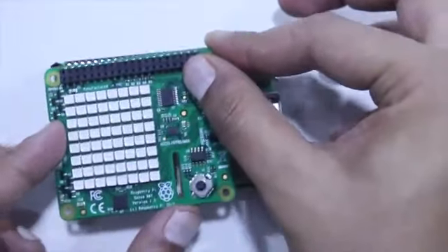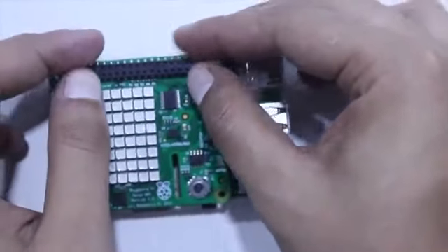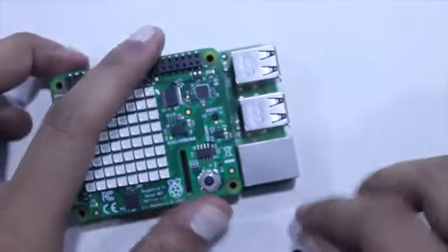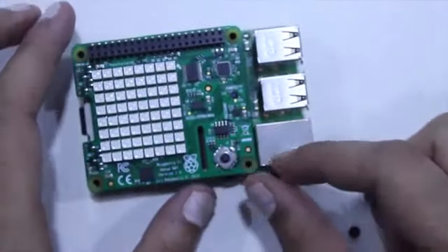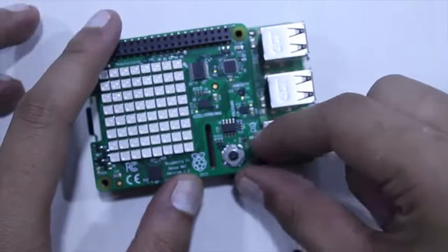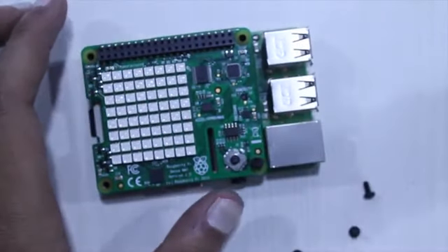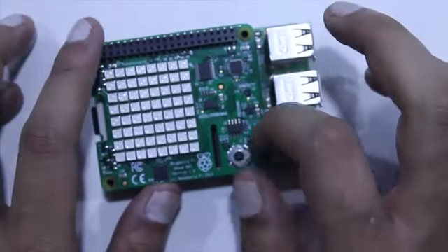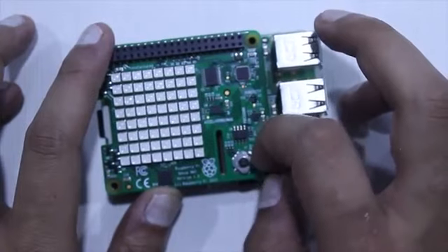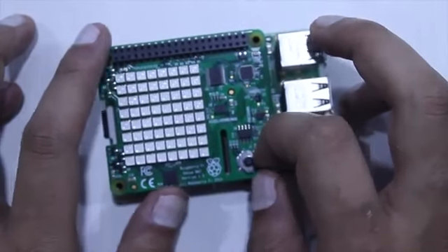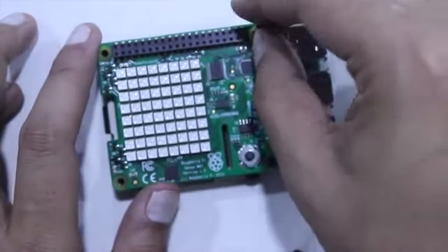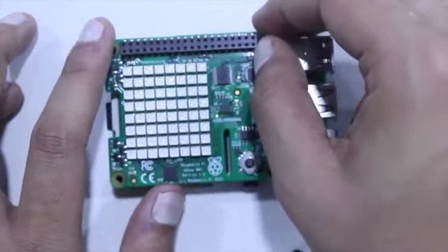It simply sits on top of the Raspberry Pi. Just make sure the alignment is correct, and once you've done that, push it on top and the pins will merge accordingly. Then you can place the 4 screws across the different ends and tighten it up. Once you're done with this, you can use the Sense HAT for various purposes. We'll use it to measure the temperature, the pressure, as well as the humidity in this room. It has different sensors present on it and we'll be using them for today's demo.